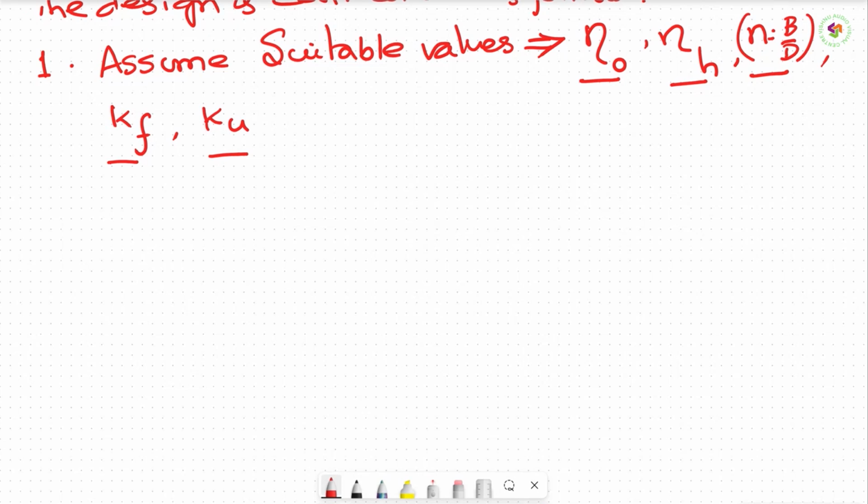They may ask you to find out the vane angles, or to determine the diameter of the runner and the width of the runner. Sometimes they even ask you to do the power calculations. So how to proceed? Your first step should be to calculate the discharge. This is the first thing.